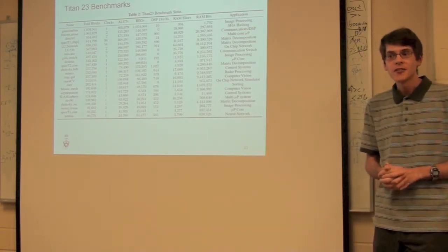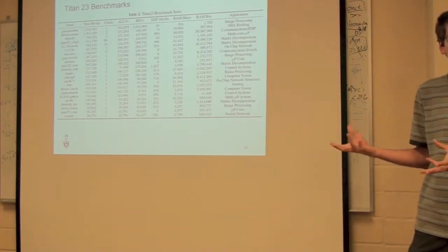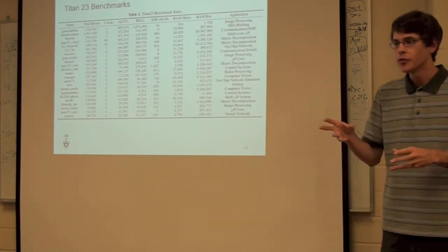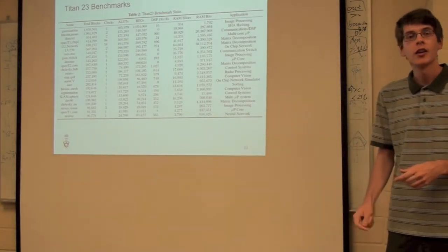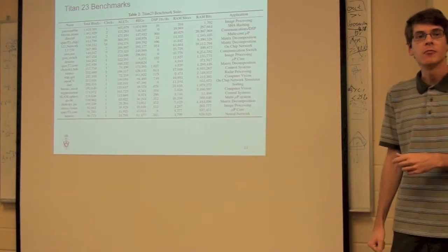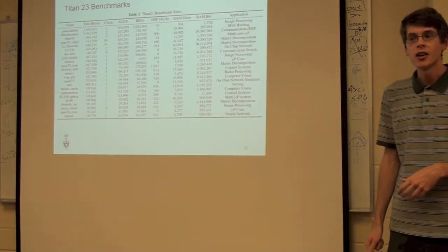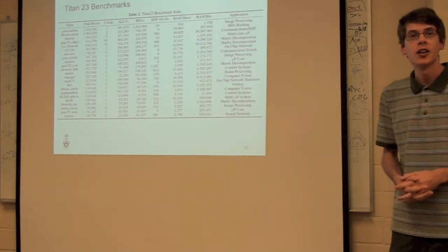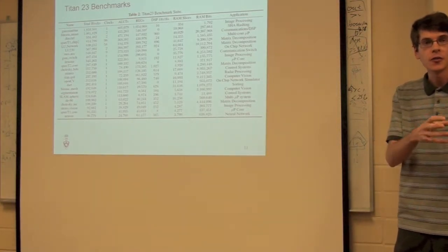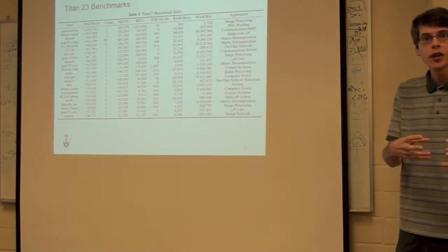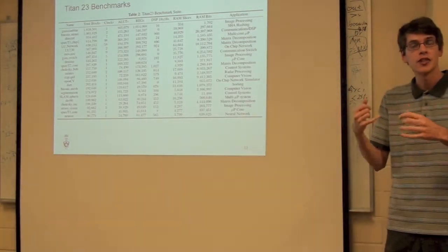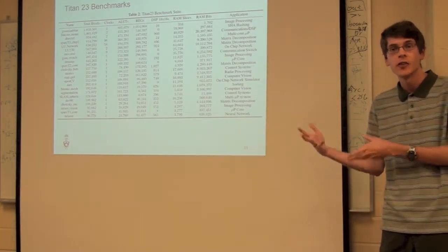Well, the challenge to that is that the raw netlists are quite large, particularly for the large benchmarks. If you extract the file from the web link, the extracted file is about 33 gigabytes of netlists from a couple hundred megabytes of HDL. So we don't want to distribute too much more than just the basic ones. Now we give you the VQM as well, which is the output of Quartus. So if you want to play with how the conversion tool handles it, you can use our conversion tool and play with the options, and without having to rerun Quartus, still generate variations.